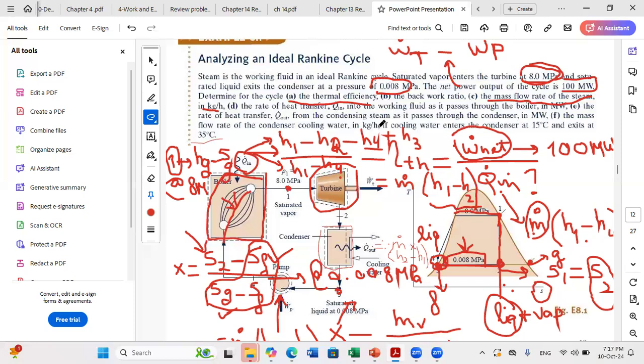So you determine what is the mass flow rate that you need of water, and you can find what is the maximum temperature I can heat to, and based on your calculation, you decide for what application you can use this water. If it's good for swimming pools, if it's good for domestic hot water needs, if it's good for underfloor heating, etc.